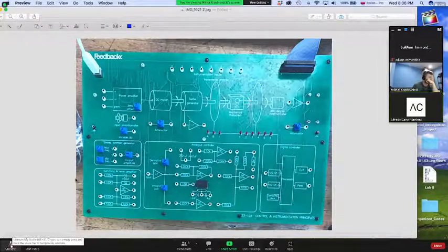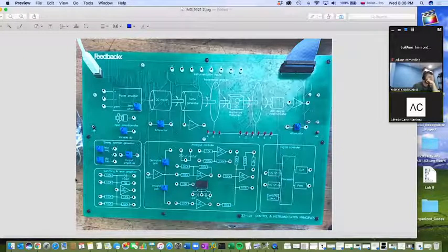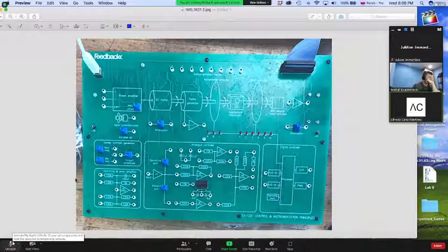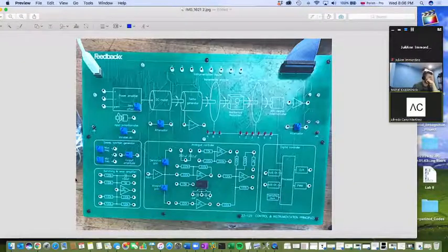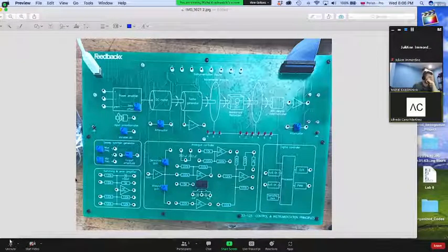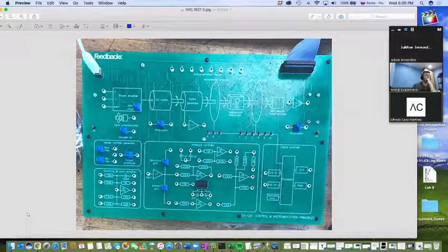So that is why there should always be a proportional, and then you just add whatever you need in order to make the response a little bit better, to make it faster, to make it more accurate, and so on. Basically, the signal driving this thing is the error, and that is why you must have a proportional channel in there. You see what I'm saying, Julianne? This relates to the whole idea of having a feedback system at all.